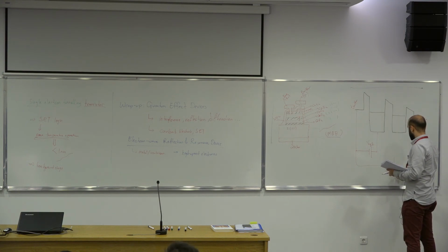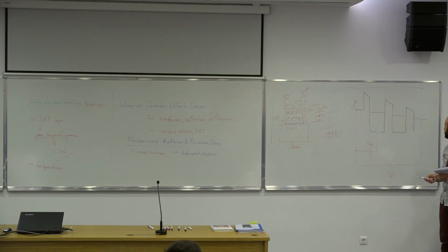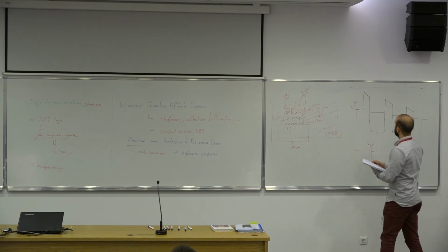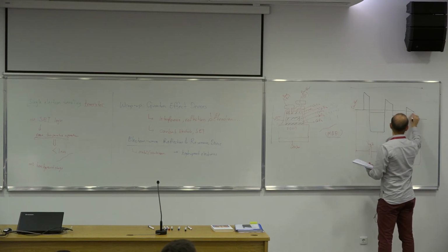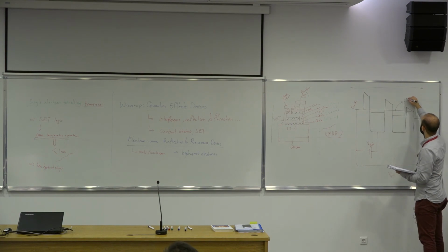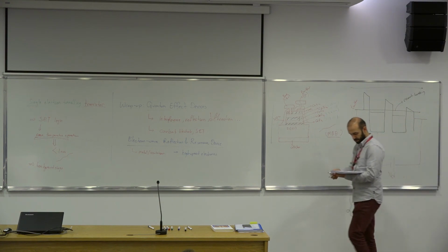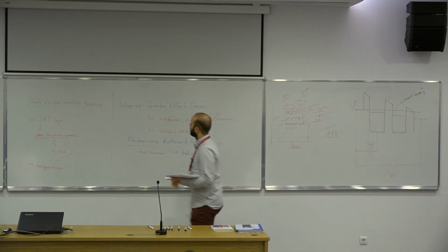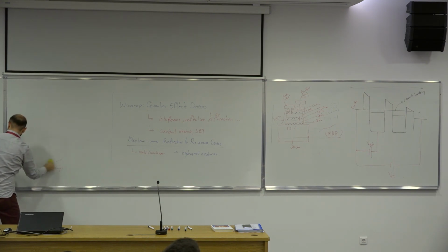Okay, and then this one is VCE. Okay, collector to emitter. And an electron that starts its journey from the emitter side will do resonant tunneling through these calcium fluoride layers to reach here. Let me draw what I mean in this IV curve.